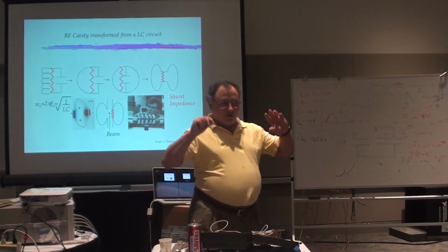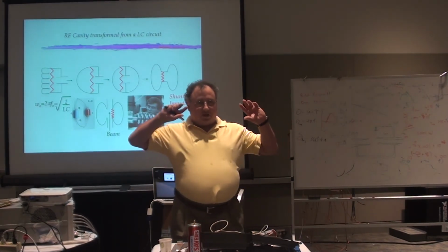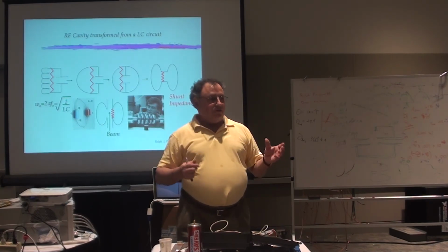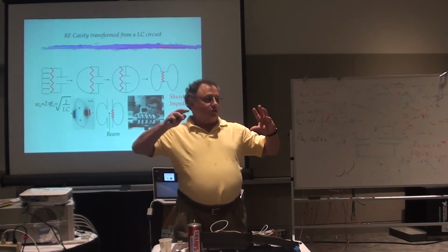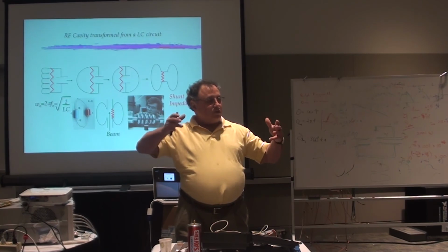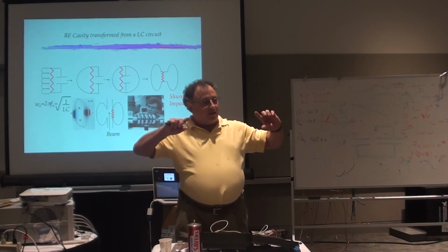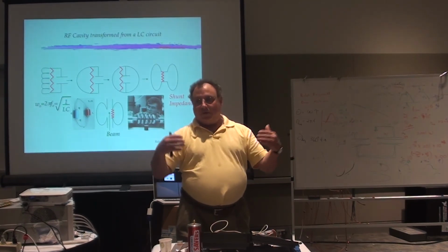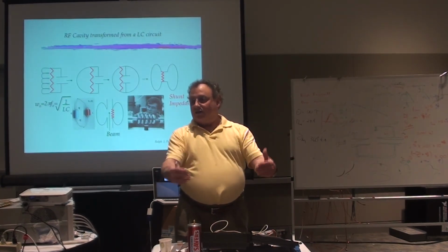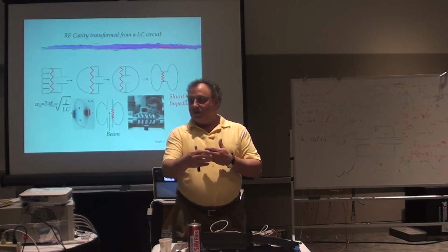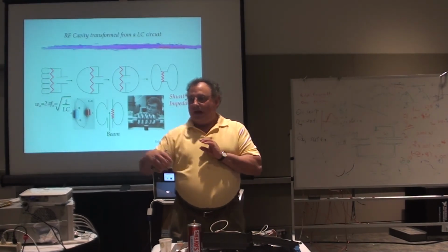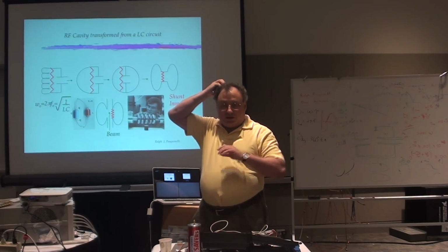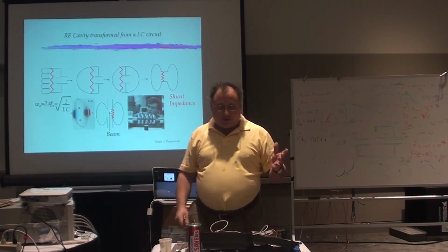So you'll see when you're over there that one of the input couplers is a loop, which couples to the magnetic field. And many cavities use this technique because it allows you to tune the coupling value by just rotating the loop that's at the end of the coupler with respect to the volume of the cavity, and it couples in a variable amount of flux to the cavity and actually tunes it so that you're in resonance with your 50 ohm input and whatever shunt impedance it transforms you to. So you'll see that that's the capability of doing that.